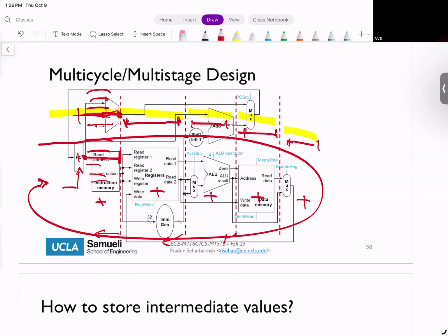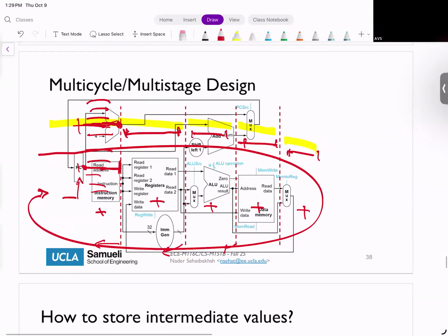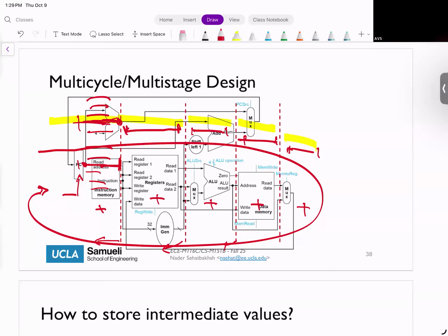Yes. The question is, what is the difference between this and pipelining? Pipelining means that now I introduce instructions and feed them into separate stages separately. For that, I need to also take care of my controller, and I need to change my data path. Here, I'm just breaking down things with registers. So I'm only introducing registers in my data path. I'm not changing anything else.